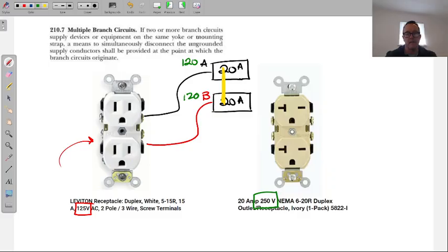By the way, the other reason we know this is 15 amps is there. This is what 20 amps looks like. It doesn't have to be this little sideways one. I just like that one for differences on these two. It can be vertical as well. It doesn't have to be horizontal. So you have both. You have 20 amp outlets that look like this. You should have those kitchens, living rooms, garage, outside outlets. There's a lot of places in which the 20 amp outlet has to be. We'll look at those. This, again, like I said, this article shows us all of that.